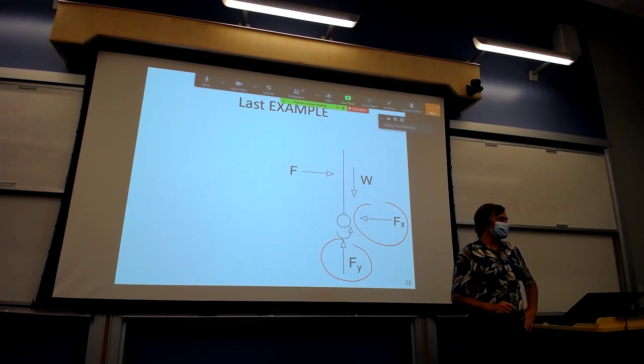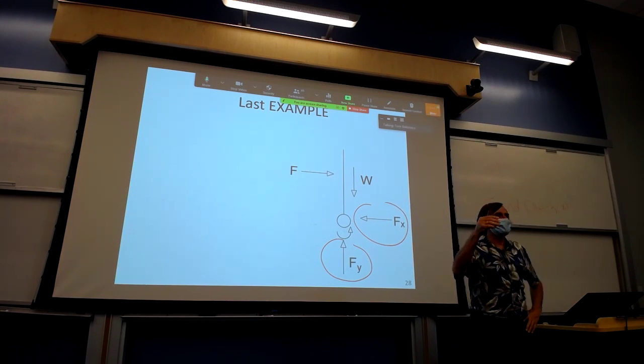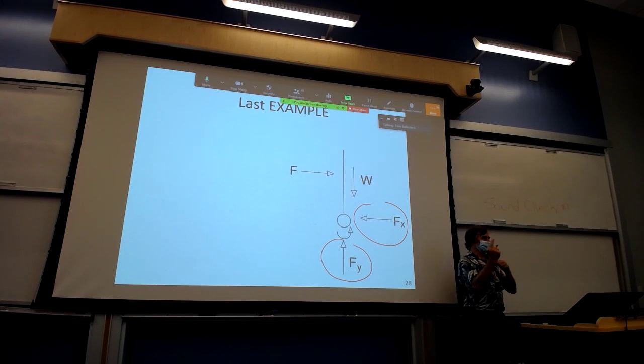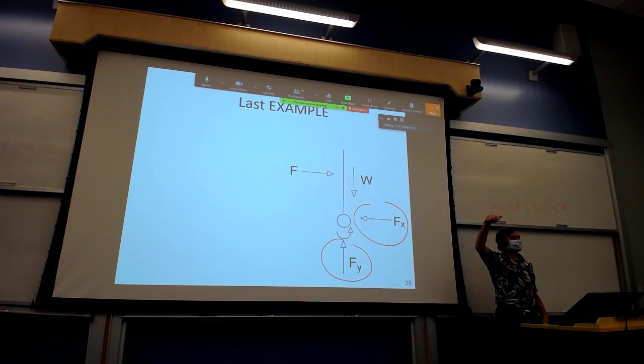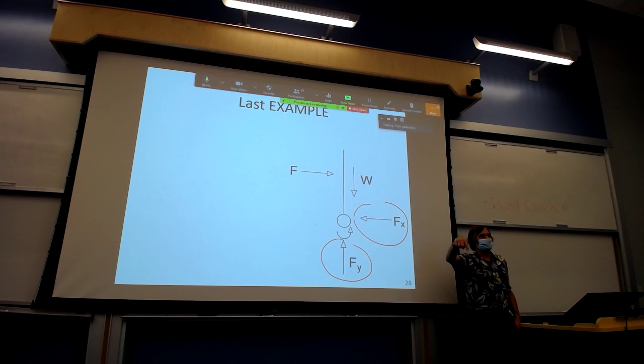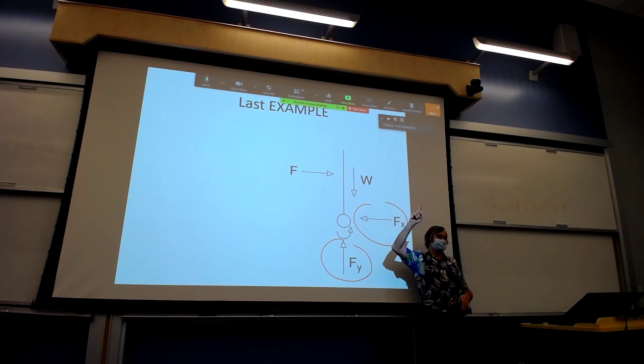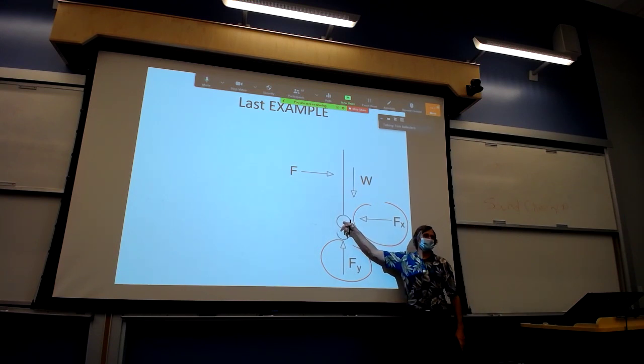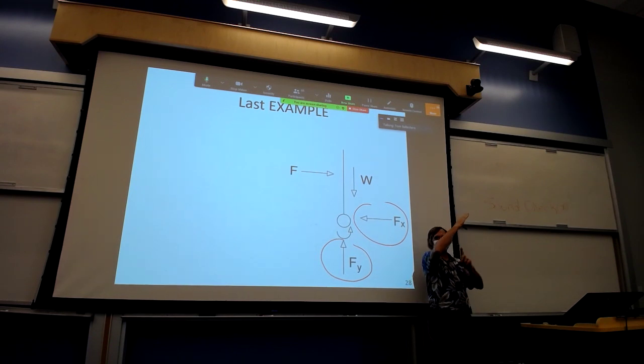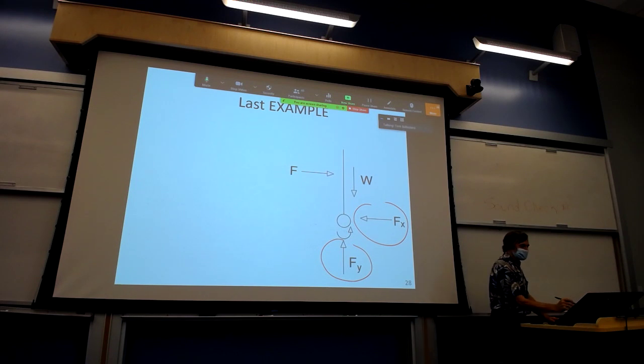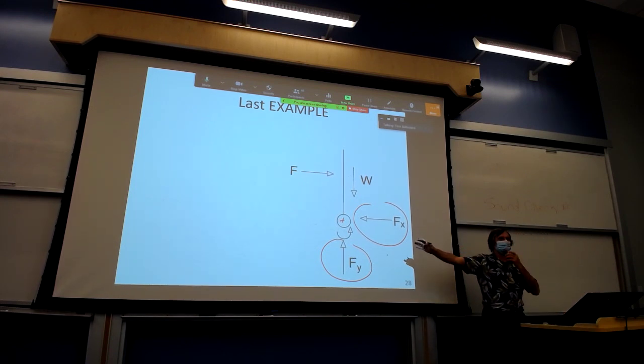It is 0, yes. If the forces act through the point of rotation where you're doing analysis, the moment arm is 0. Fy is a vertical force. The gate may have a weight in some problems. That probably also acts through, if you have a vertical gate. If it's a vertical gate, it's going to act through the pin. If it's not a vertical gate, nope, now you have a moment arm, don't you? Okay, so again, sometimes doing the moment equilibrium, you get rid of those 3 moments, weight, Fx, and Fy, because they're all acting through the point of rotation.